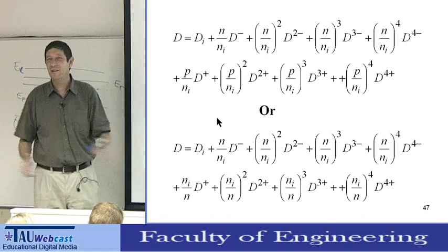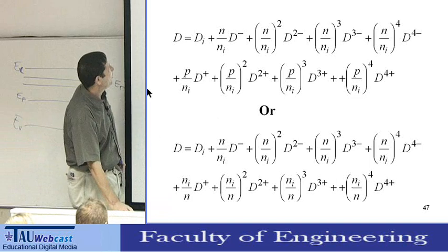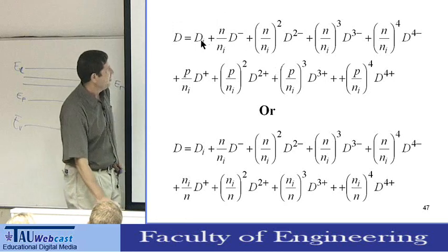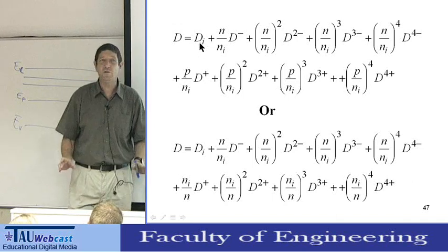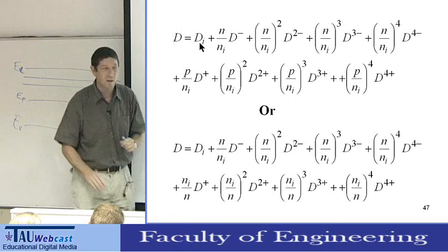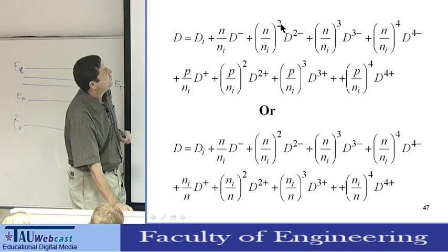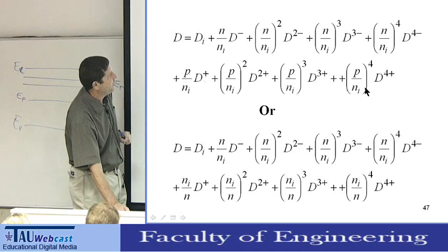analytical expression. The one expression fits everything of the diffusivity. This is the diffusivity of the interstitials, Di, sorry. This is intrinsic diffusivity. This is the diffusivity if we don't assume this effect. This is the diffusivity for the negative charge. This is the diffusivity of the doubly charged, triple charged, 4 charged. And this is for the vacancies which depend on n. The part which depends on the hole concentration also has 4 components.